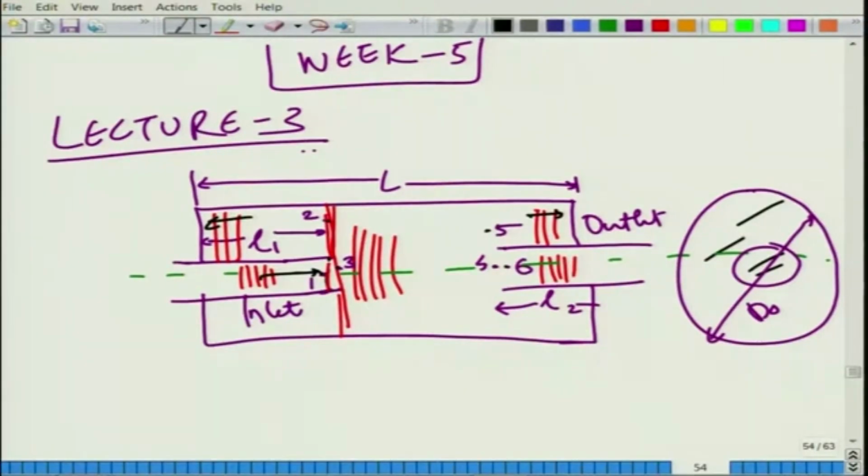So, this is actually a beautiful analogy between acoustics and electrical circuits. We will soon discover that as well and try to draw some electrical equivalent acoustic circuits for this muffler configuration, obviously assuming planar wave theory. And velocity V1, the acoustic mass velocity, has to be conserved.